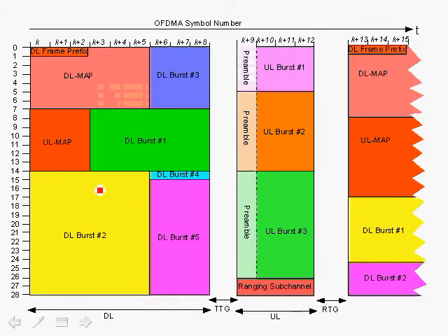Here we show a very important picture in order to understand OFDMA. In this case let's talk about time division duplex. Here we have a frame, which is a TDD frame, and as we mentioned before, you have in this region a downlink followed by a TTG, which is the transmit to receive gap, in which then the subscriber stations go from receive mode to transmit mode and transmit back data to the base station. So these two constitute the downlink and uplink, all within one TDD, and this is one frame.